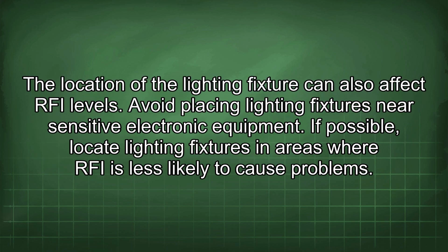The location of the lighting fixture can also affect RFI levels. Avoid placing lighting fixtures near sensitive electronic equipment. If possible, locate lighting fixtures in areas where RFI is less likely to cause problems.